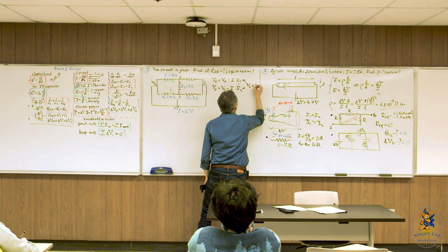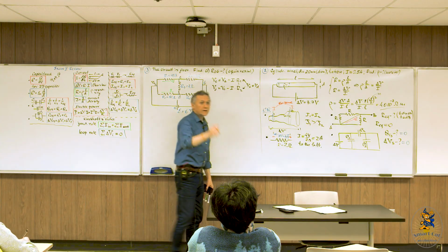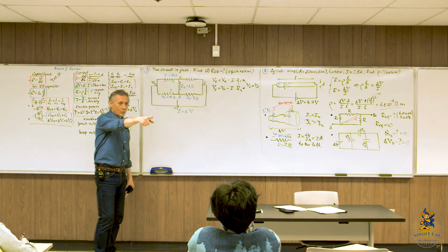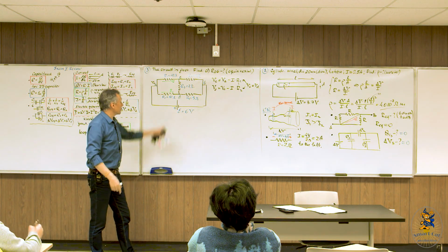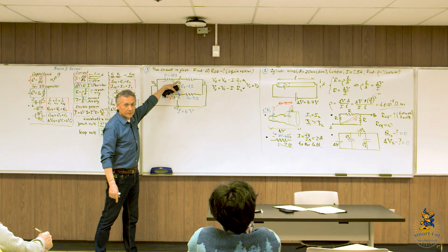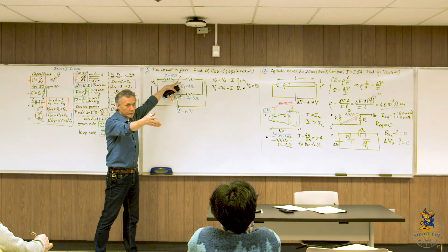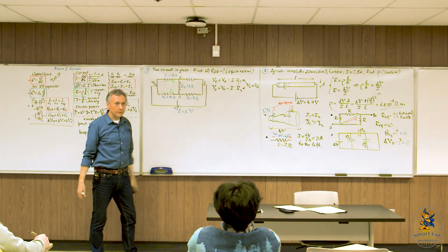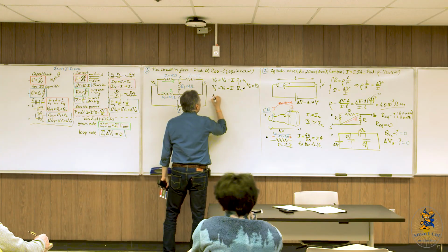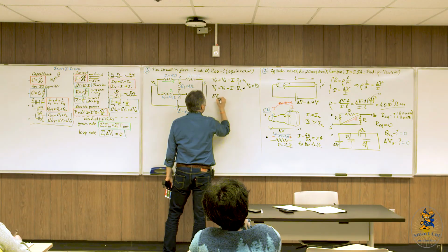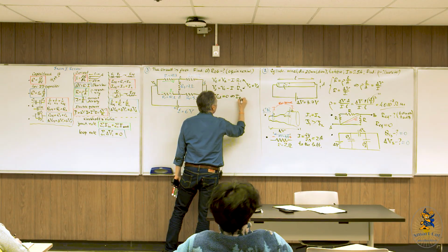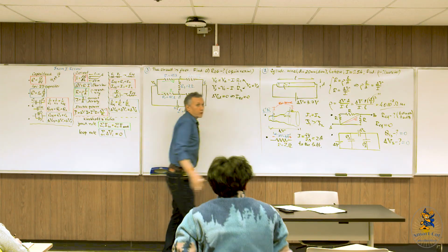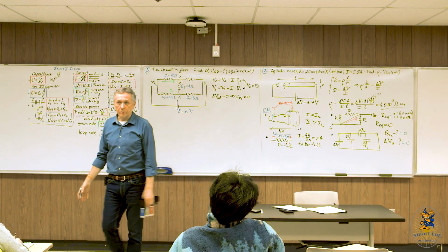So Vc equals Vd. And as a result, you said something about zero. What is zero? Potential difference across the resistor. This resistor is zero. As a result, current, as you said, will be also zero, right? So delta V across CD will be zero. And of course, current through R5 will be also zero. So essentially, that resistor doesn't do anything in this circuit.